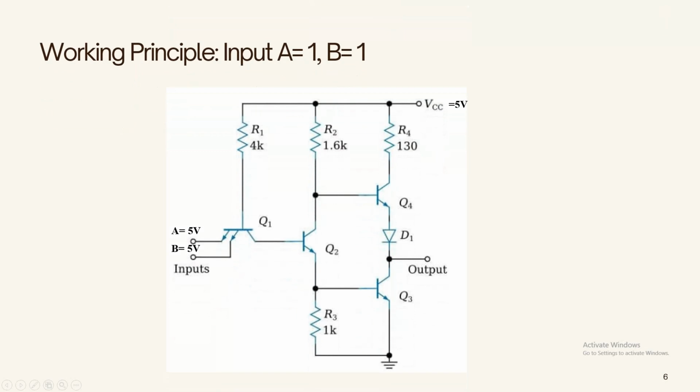It cannot generate 5.7 volt. So let's assume we have the most voltage, which is 5 volt at the base of Q1. So if we have 5 volt at the base, then the collector would be 4.4 volt, if we assume its base to collector junction is in forward bias mode, and there would be a 0.6 volt drop at the base collector junction.